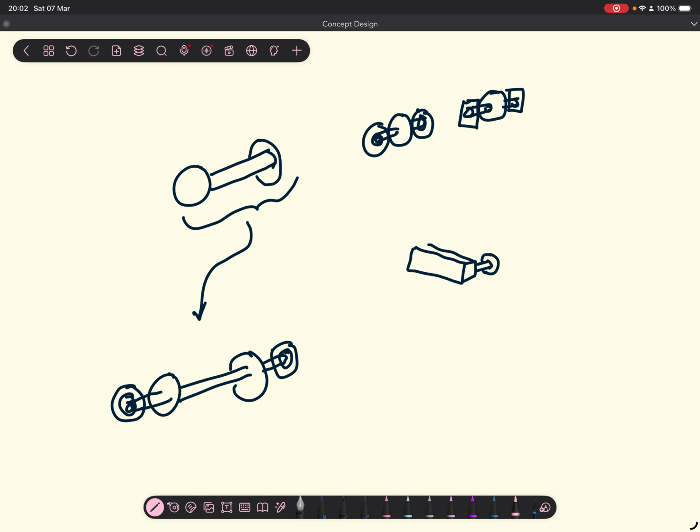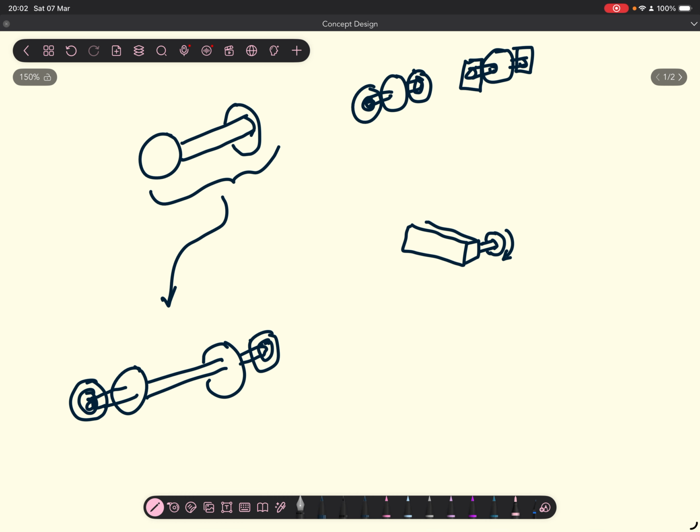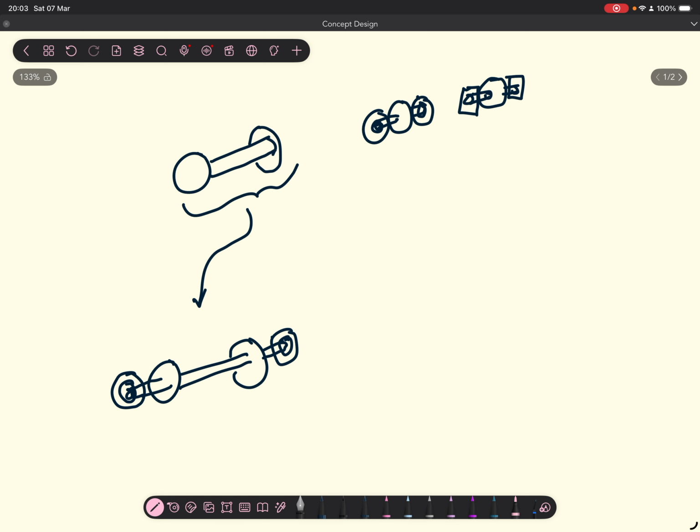We want the beam to stay stationary while the wheels rotate. Well, we want the beam to move forward, but in order for that to happen, the wheels need to rotate, and this must stay stationary. And in order to do that, we can put a bearing, right? So the bearing will allow the wheels to rotate without having the frame itself rotate. Okay, so we need to put bearings in these locations, and to do so we'd need some sort of bearing housing to contain the bearing, basically.